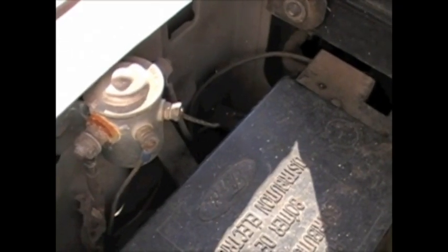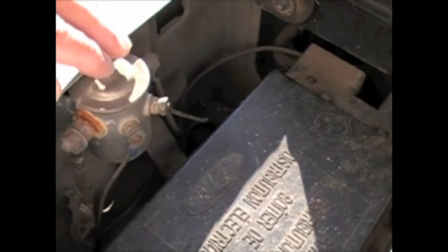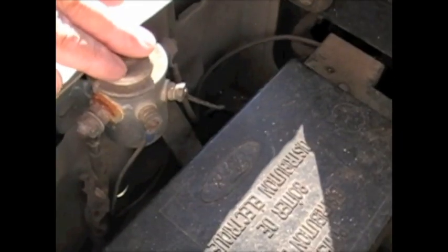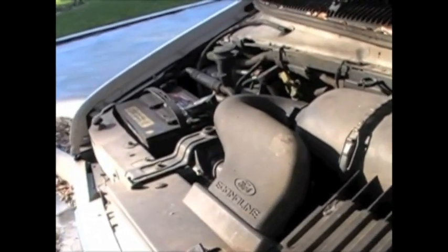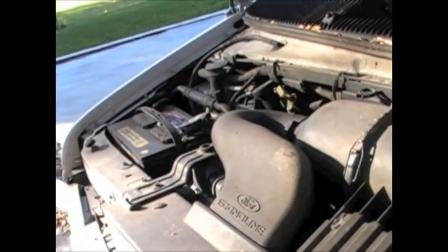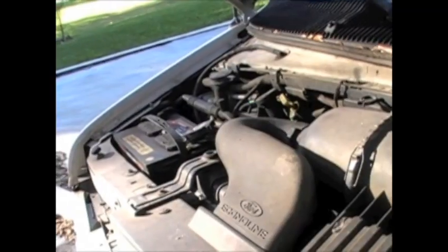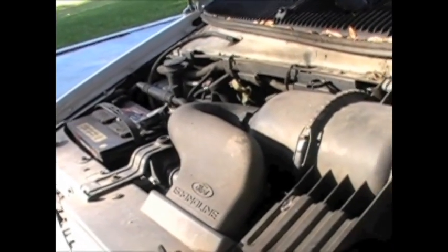But when the van is turned off, there is not a complete circuit in the relay, and the battery in the back is not drawing power from the battery that operates the van, so there is no danger of draining that battery down and me not being able to start the van.